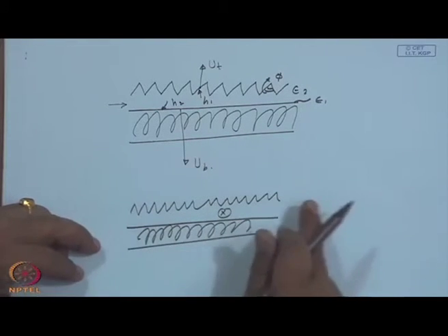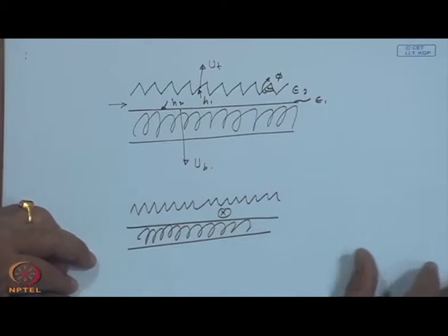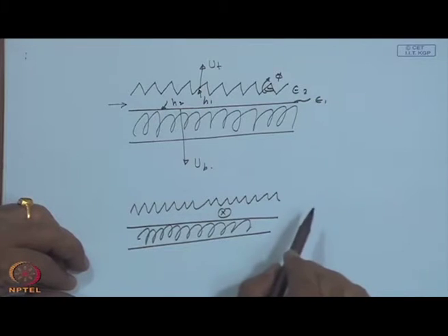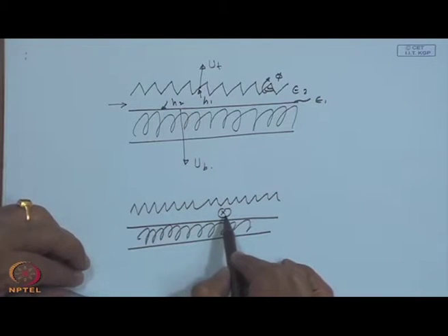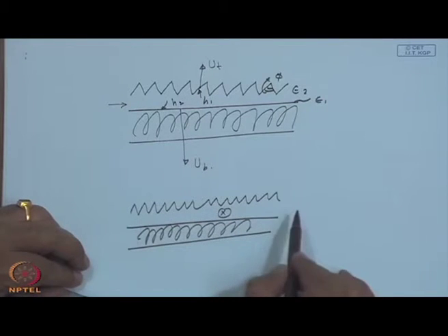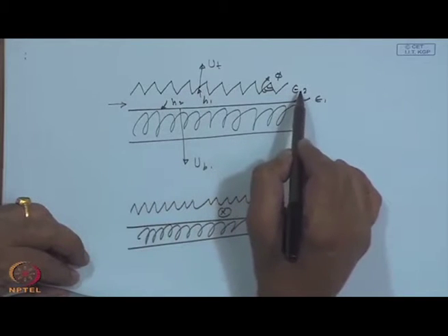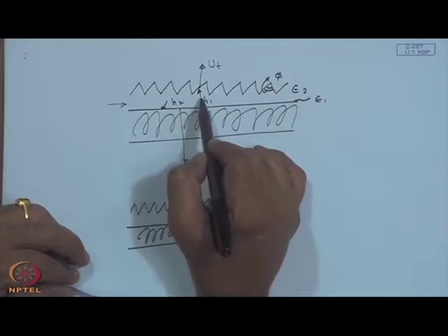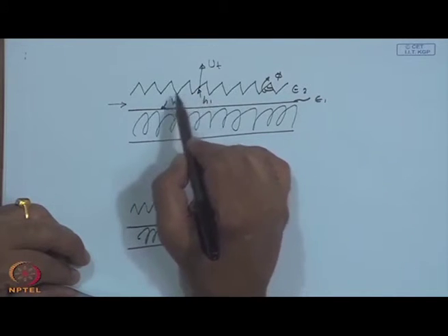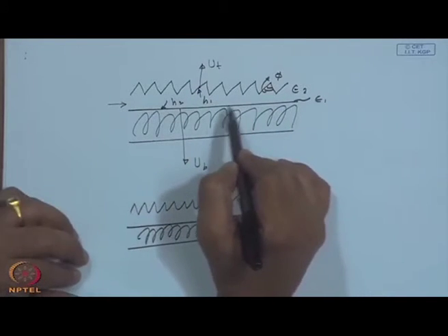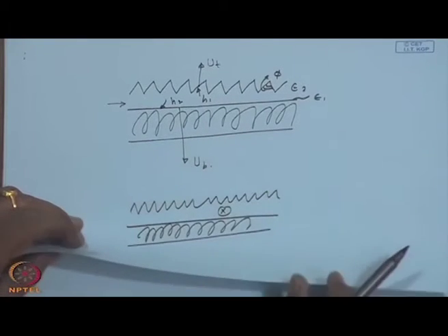Still it has a larger extended area compared to a plain plate. Consequently, it may be having better heat transfer characteristics than a simple flat absorber. However, here the phenomena is different. It aids augmenting heat transfer by breaking the development of boundary layer as well as providing mixing of the fluid.